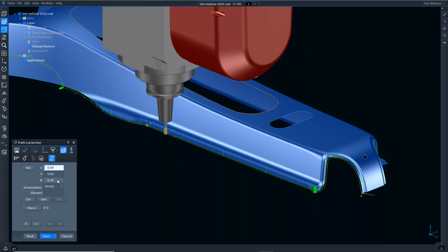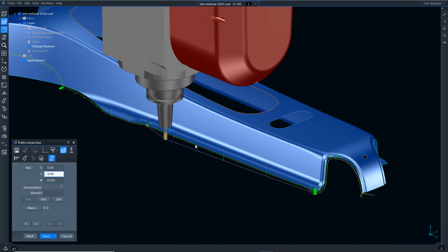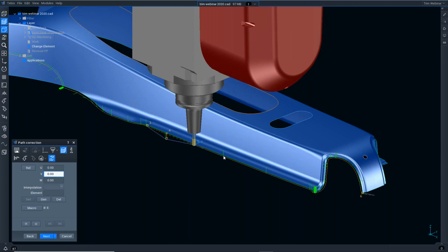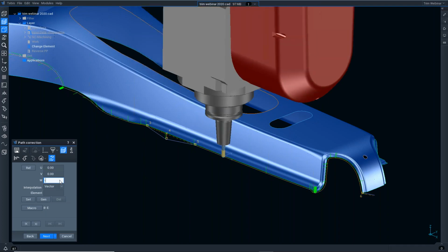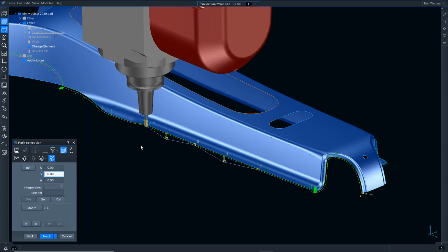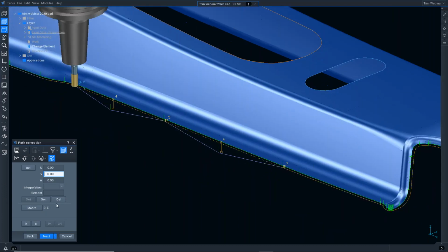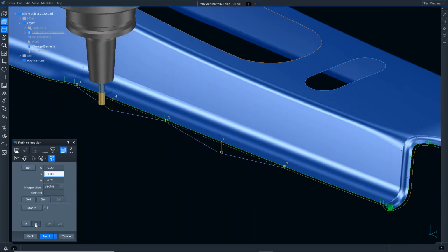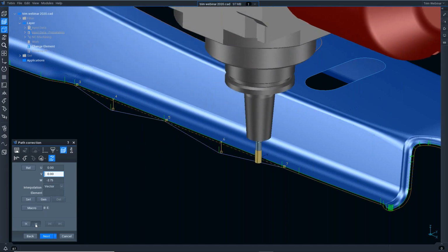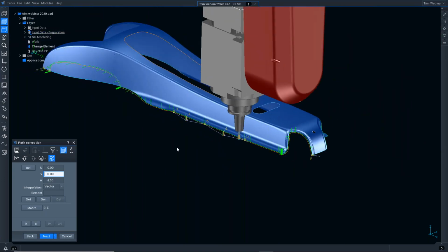So if I come down to this next area here now, we can do some minor adjustments along the tool path. And this now gives us the sort of tool path that will spread the tool wear evenly along the flute, whilst also maintaining the cut geometry and the cut position of the tool against the component, so as not to lose any dimensional accuracy.